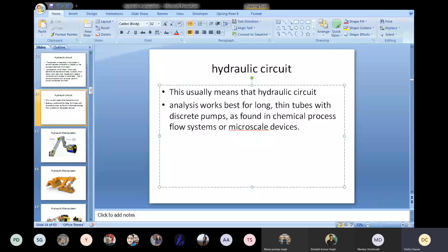In the closed loop circuit, the motor return is connected directly to the pump inlet, and to keep up the pressure on the low pressure side, the circuit has a charge pump, generally a small gear pump, which supplies cool filtered oil to the low pressure side.